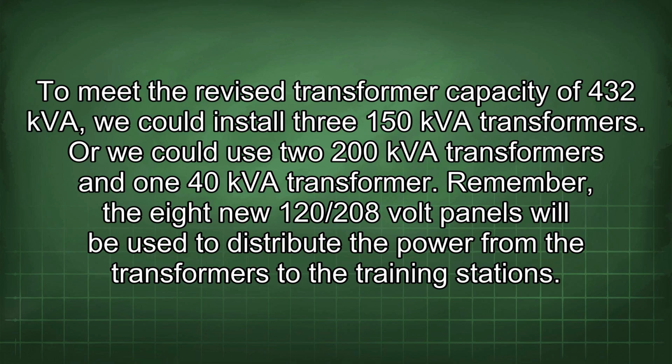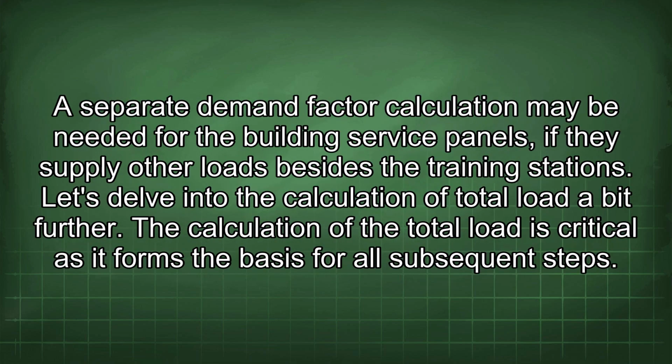Remember, the 8 new 120/208 volt panels will be used to distribute the power from the transformers to the training stations. A separate demand factor calculation may be needed for the building service panels if they supply other loads besides the training stations. Let's delve into the calculation of total load a bit further.